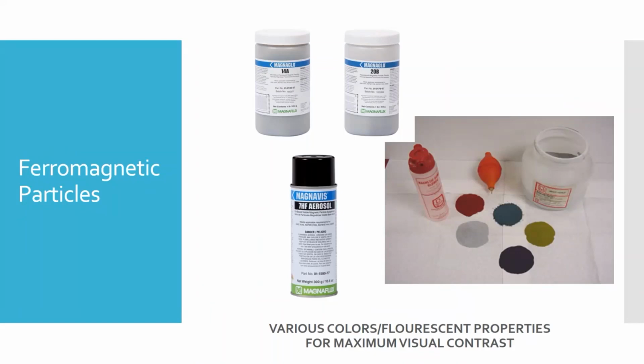But you'll get what's called draw out, and that is as you test items, some of those particles stay stuck to them even when you're done. You go clean the part in a washer somewhere, and now you've just reduced the total number of particles that are in the tank. So over time, the level in a testing bench is going to drop.